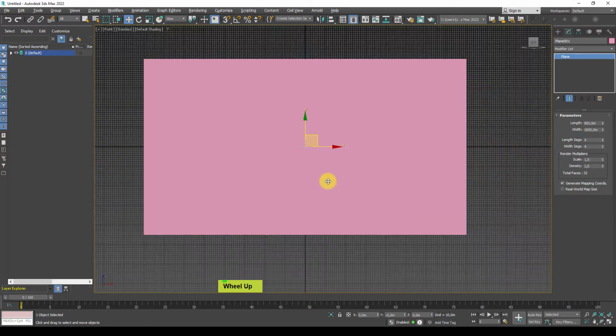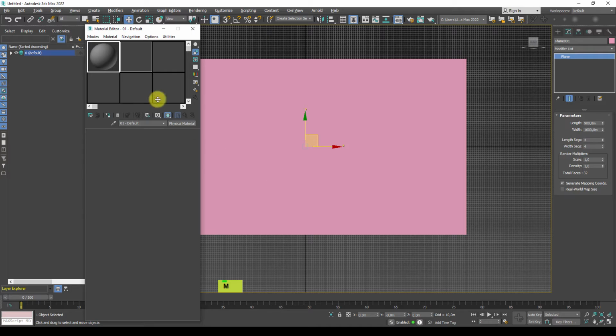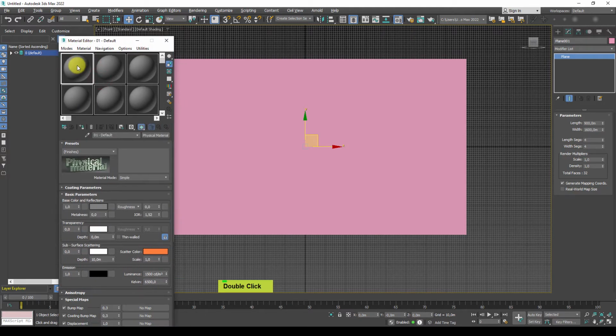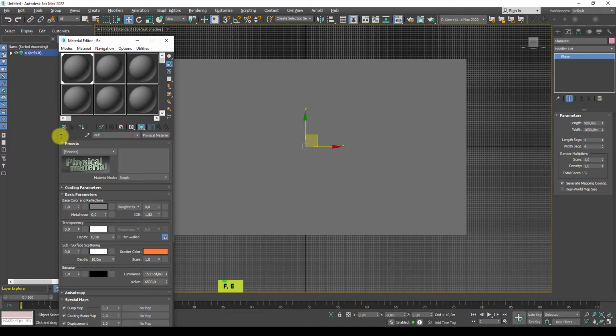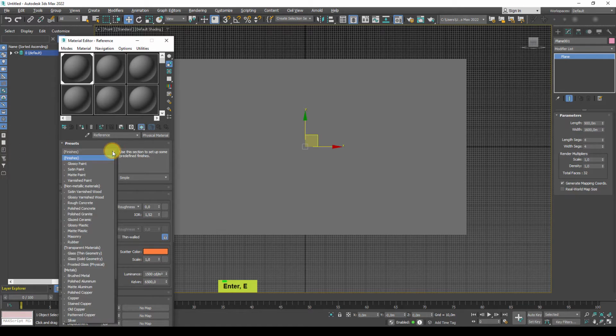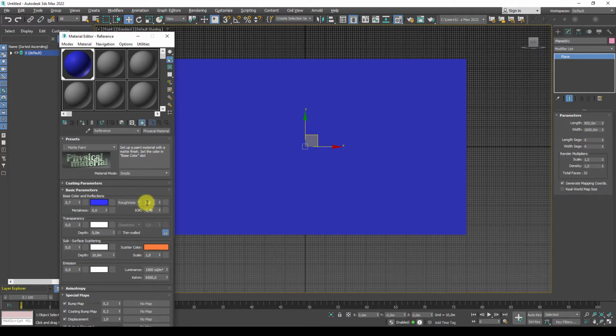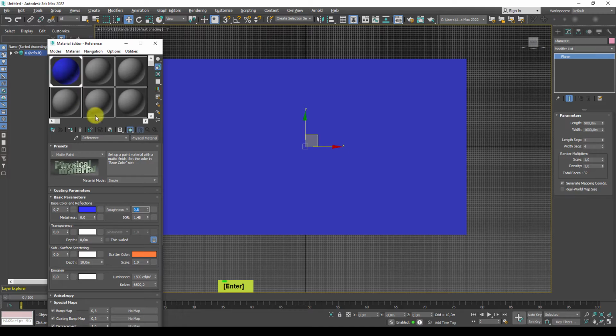What else? First, right away, open up Material Editor, and if you see the slate editor, in the modes you can switch to compact material editor. Let me drag and drop it and rename it to reference. Basically it should be a matte material with a roughness that's 0.6. It's not perfectly matte. We can set it higher, 0.8. And that helps a bit to reduce the shine. Some shininess could be okay even for stones, so that may be good, but not in all cases.